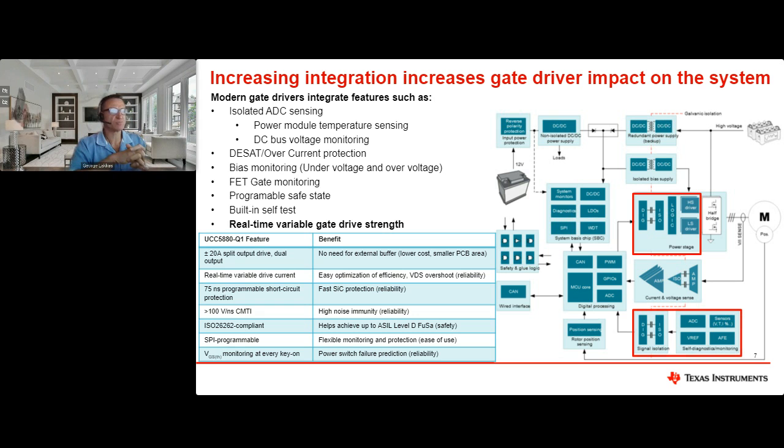And so it's quite flexible. We also include a feature we feel is quite differentiated, which we call gate threshold voltage measurement at every key on. Essentially, you'll be able to see and predict if the power switch, the silicon carbide FET, is beginning to fail, and that's also included in the driver. So today's drivers are vastly different from yesterday's drivers.